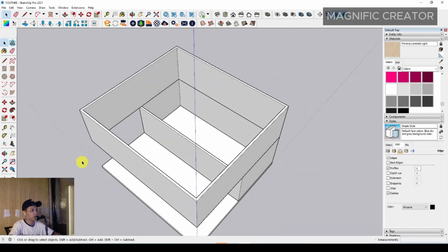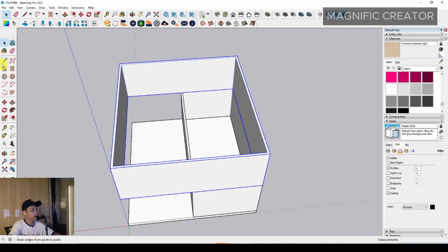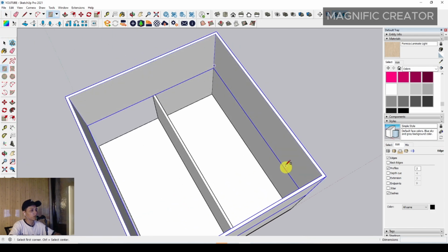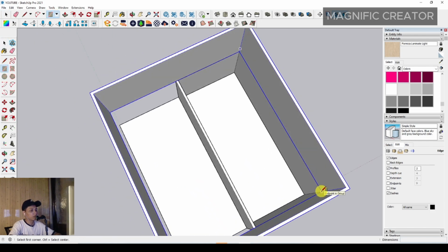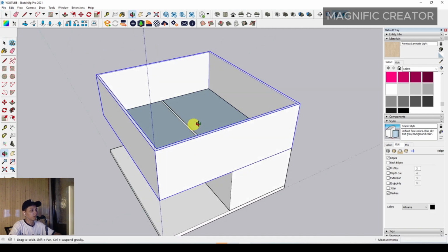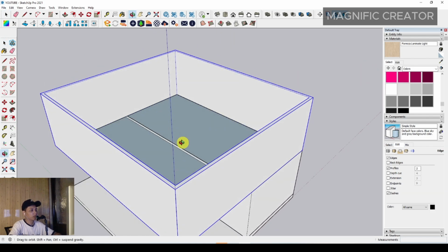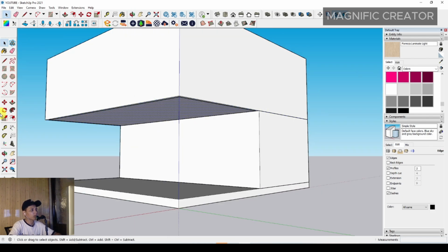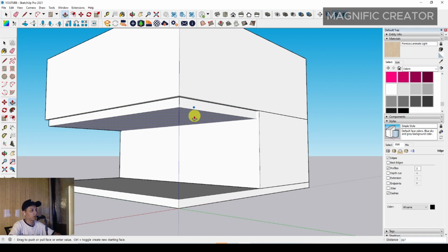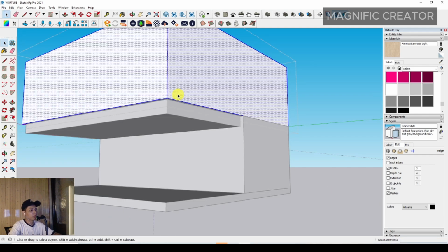As we can see on the video, we can then make it group, and don't forget to make the floor on the second floor with a rectangle from the front corner to the back corner with a diagonal range. Then we can push it down around 500 millimeter.